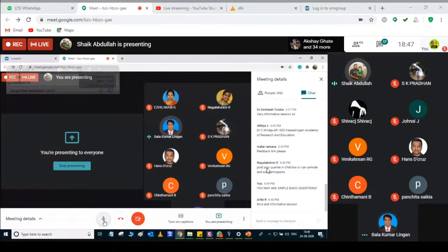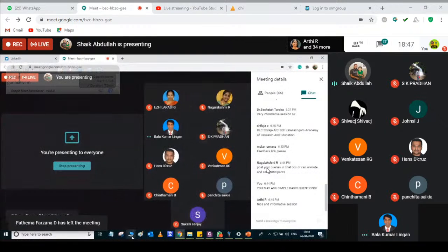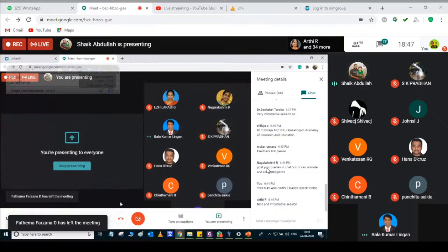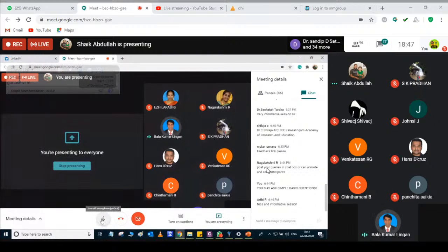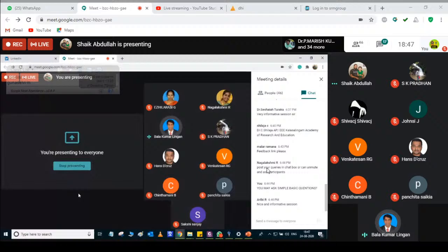This is a very simple thing, I think they are expecting answers from some other participants. If they are not asking, we will ask the questions to them. The motor typically takes 6 to 7.2 or 8 times the current. If it is an energy efficient motor, it normally takes 10 to 12 times the initial starting current.